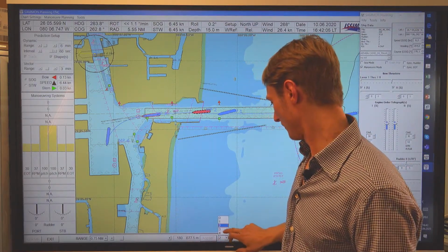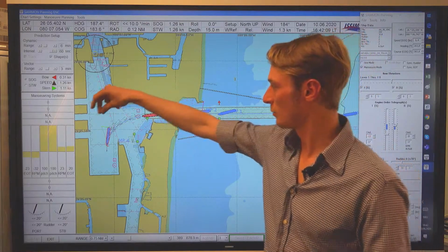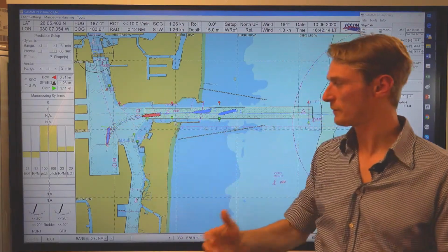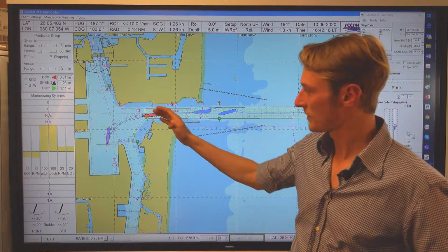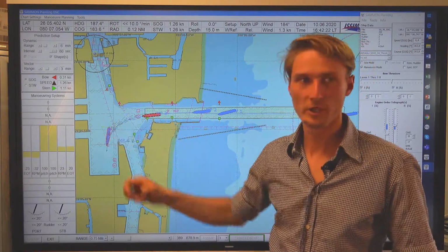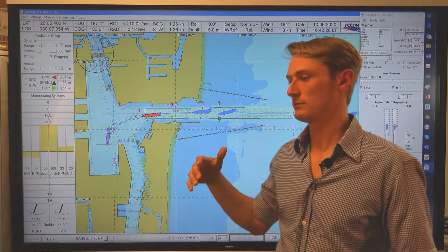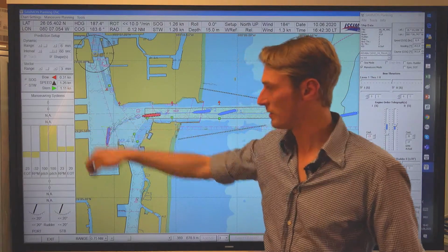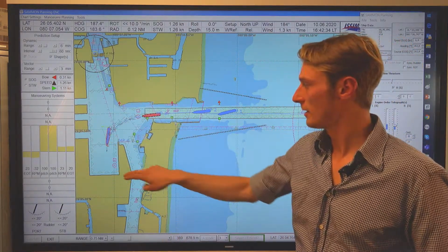And where do you see the results? The results are to be seen immediately. We set the wind and we end up, of course, further on the east side. And what we need to do here is to maintain a higher speed until we initiate the turn, or turn with a smaller rate of turn in order to stay on the western side of this basin here.